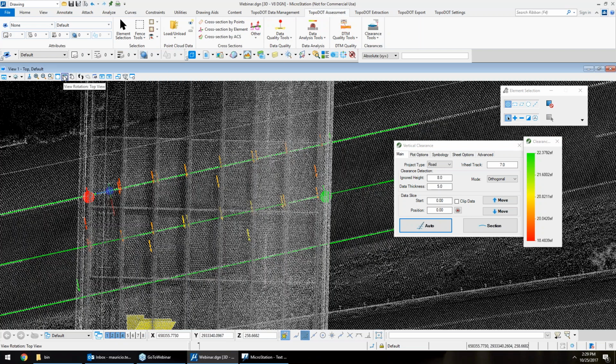When you pick your data thickness, the way to think of it is that we have one super elevation reference for that data thickness. So you pick a thickness short enough that the super elevation of the road, the gradient, the slope of the road, is going to be the same over 5 feet. Nothing's going to happen much. You don't want to make that 100 or anything like that. You start changing the elevation, getting curves, so you have some average of everything. But basically, it takes that one reference and then it goes every 5 feet and looks for it. There's a way of putting dots in the top too, I think, but I don't know, whatever.